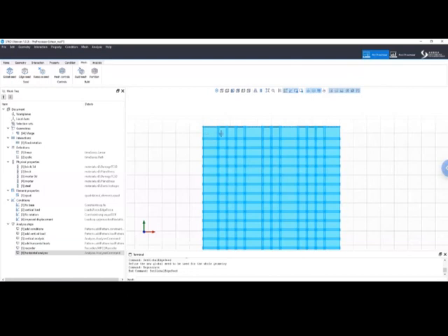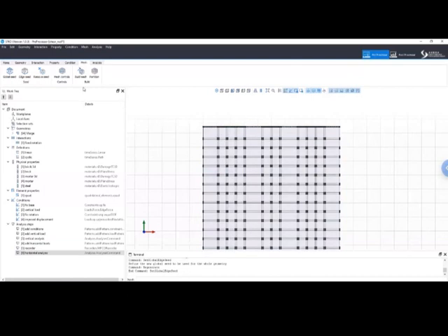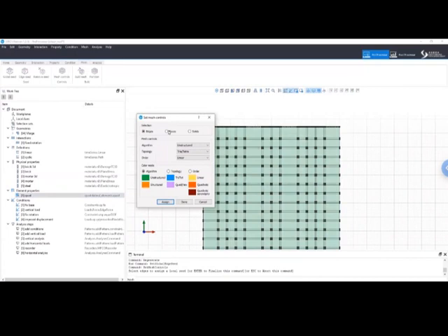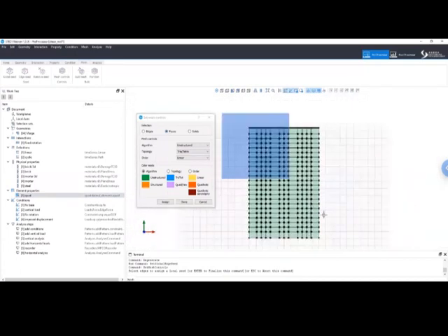By default, the element is triangular, but we need the quadrilateral one, because it should be compatible with the finite element we choose here. So we go under Mesh Controls, we go under Faces, we select all the faces, okay, and we choose for those faces a structured mesh algorithm, and the topology should be quadrilateral or hexahedral for 3-dimensional. The order, it is fine linear, otherwise we have quadratic, but in this case in OpenSees we don't have quadratic elements for the plane stress model. So linear is fine, assign, done.